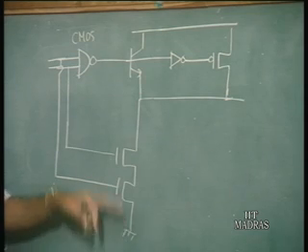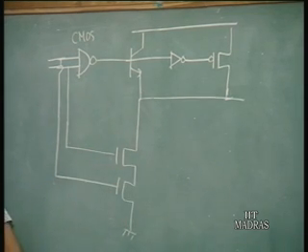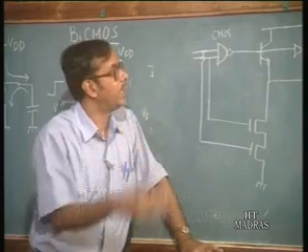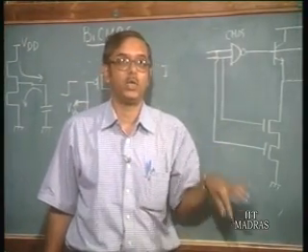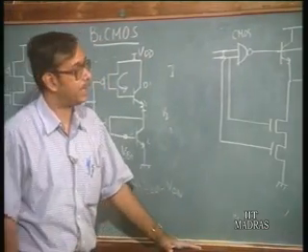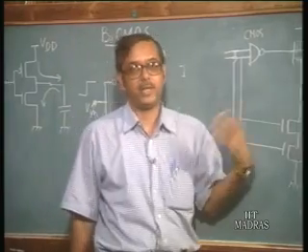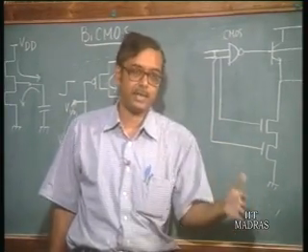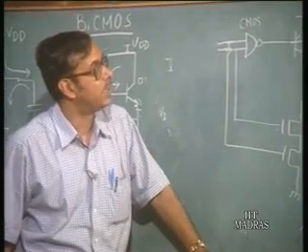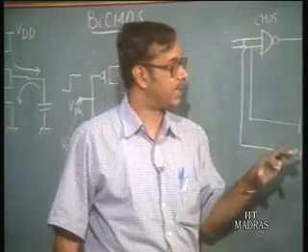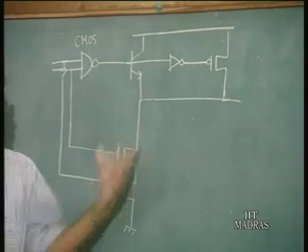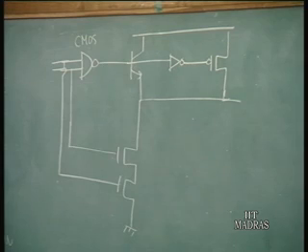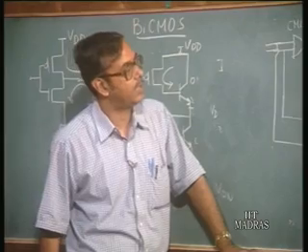At the same time, it will also go to 0 because you do not have any bipolar transistor here. So, we have full swing operation from 0 to VDD, and so a lot of these circuits are being developed nowadays for full swing operation, keeping in mind the low voltage operation. Okay. So, this particular circuit has been used in Pentium. In fact, there are different variations of these full swing BiCMOS circuits by different groups of people from different companies. But the basic idea is, for the pull down part, it goes back to the NMOS, there is no bipolar transistor, but for pull up the bipolar transistor is used, which helps to speed up the low to high transition of the output.